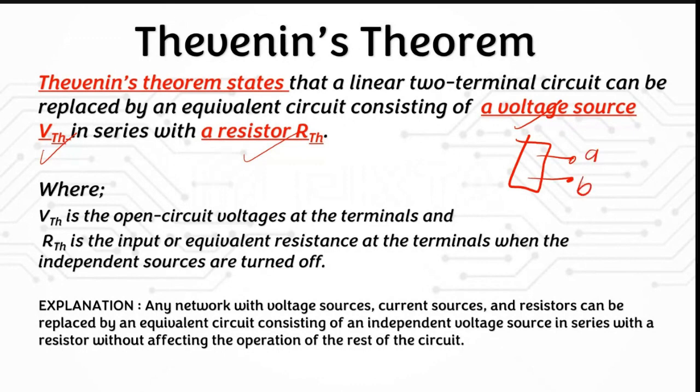The equivalent circuit has this Thevenin voltage, VTH, with RTH here. So we can replace a complex linear circuit at its terminals with this equivalent Thevenin circuit.